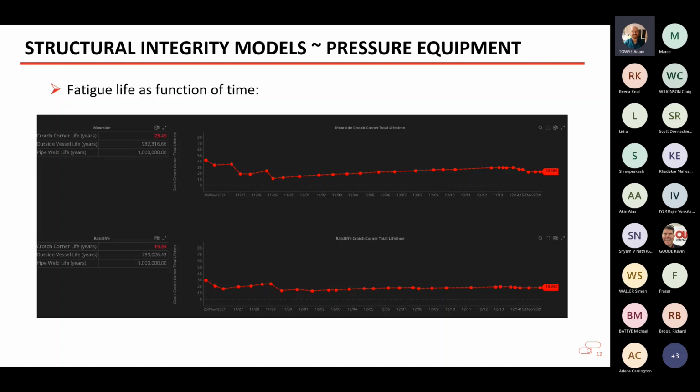Some plant might load follow, for example. It might start to shut itself down in periods of low demand, which is good for economics purposes, but maybe is not so good from a durability point of view, because you're starting to introduce a lot more startup and shutdown sequences, which can be quite damaging.